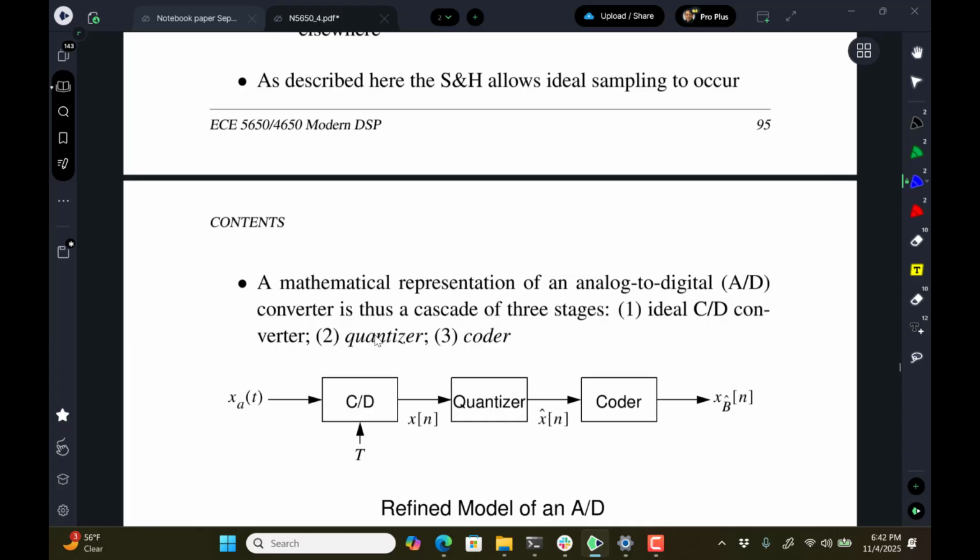So one of the team members investigated some spray paint for automotive use that was anti-static, and they sprayed the container with that anti-static paint and then created a new board, mounted parts on it, and that kept it from getting zapped. But they were very disappointed with that, for sure.